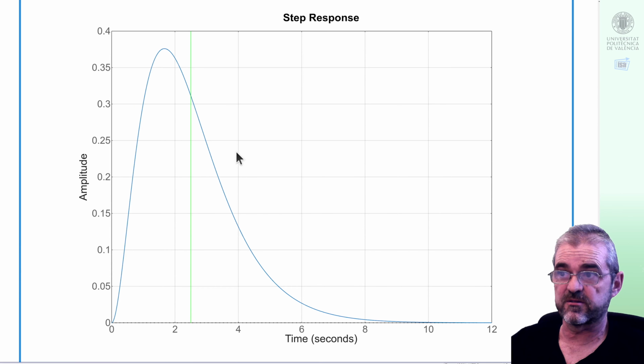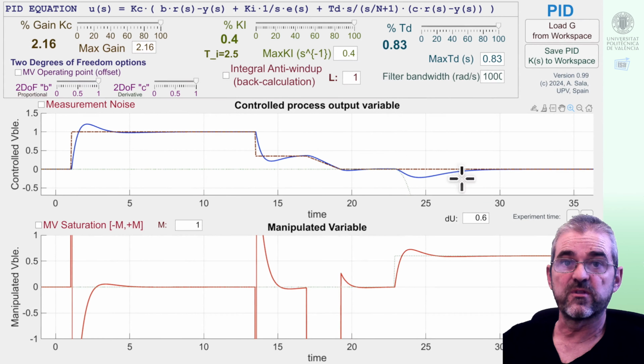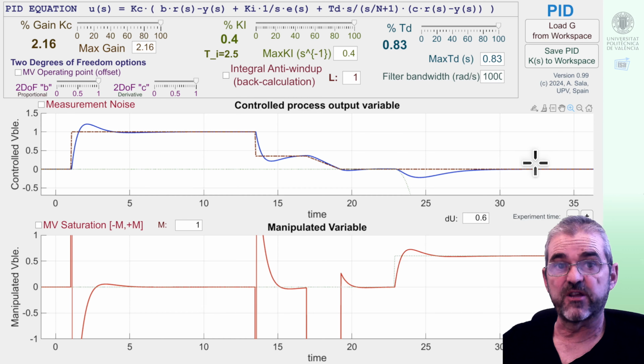And again, the disturbance rejection step response, this one, well, this is a unit disturbance plus 1, and in my application I was simulating minus 0.6, so with suitable scaling and turning it upside down, this plot is identical to this part of the plot in my simulation. So for the moment being, I've done nothing compared to what I did in Matlab.